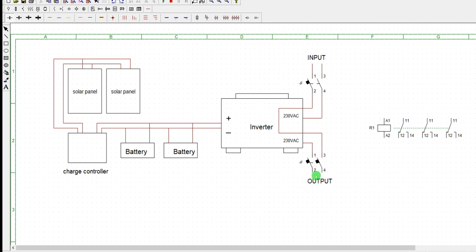This output that you have belongs to this supply. It does not come from the inverter's output. The inverter will not give you this until this power is cut off. So when this power is cut off, that is when the inverted energy will come to the output. But provided I have input here to the inverter, the output I'm getting here is not the inverted output. It's the same input I have here that I'm getting here.